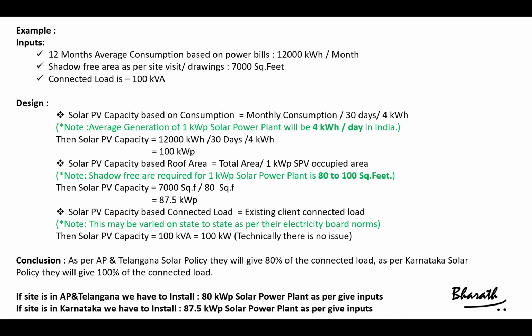So I think you got my point. I will share this PPT. You can also check your residence, and if you have any business, a commercial office or manufacturing unit, you can check how much solar plant is required based on these three details. Power bills you can get from your residence, the roof area you can visit and measure to see how much SFT you have, and the connected load you can get in the power bill copy.